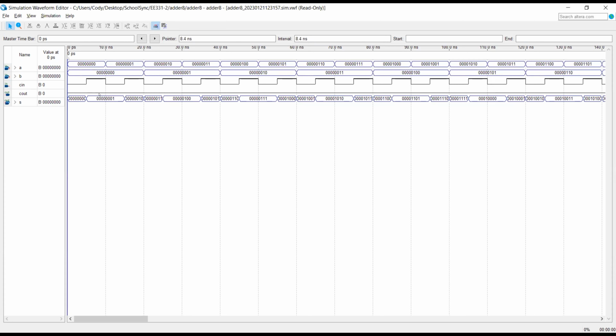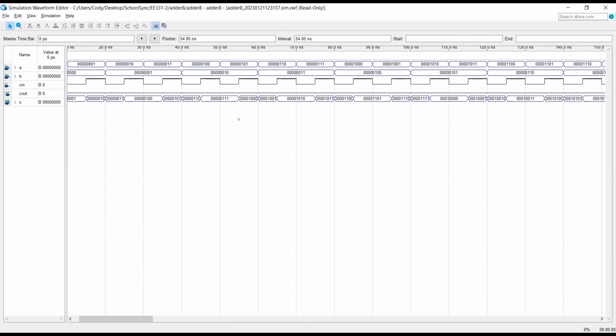Excellent. Now I go to the third stage. Now you have 1 and all zeros, and the carry is 0. What will you get? You'll get another 1. Excellent. Go to stage 4. Now I have here 1, 1, 1. So I get 1, 1. The rest will be 0. 0, 1. Yes. It's working. Okay. I wasn't sure if I had the waveform correct. No, you trace it as I did. Okay. Step by step.